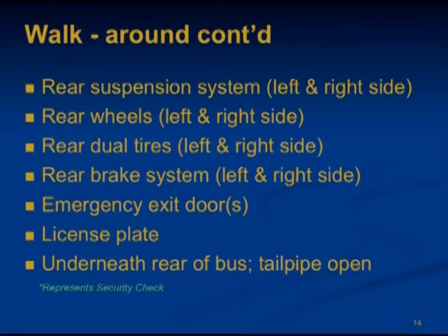The emergency exit doors at the back of the bus, make sure that the hinges are not damaged and will open or close and latch properly from the outside. Make sure that the glass is not broken and the seals around the windows are tight. Make sure that the warning buzzer works.